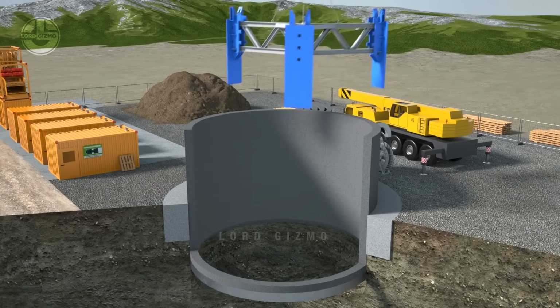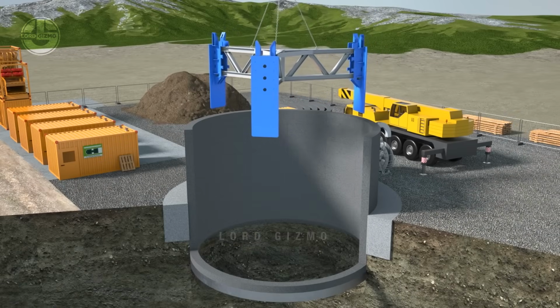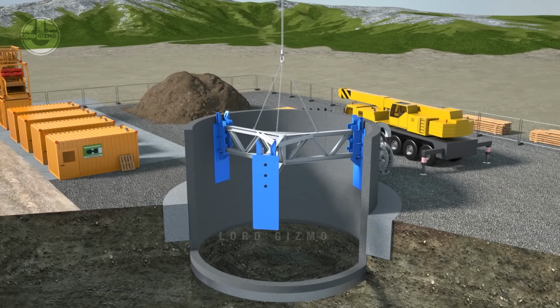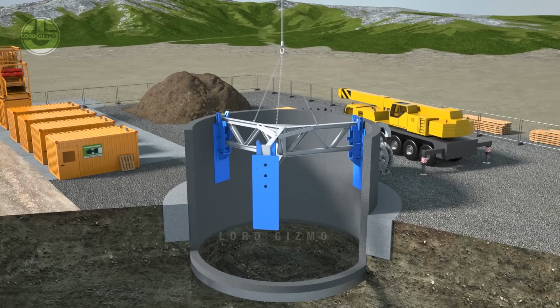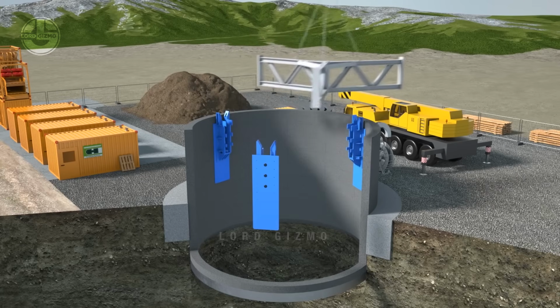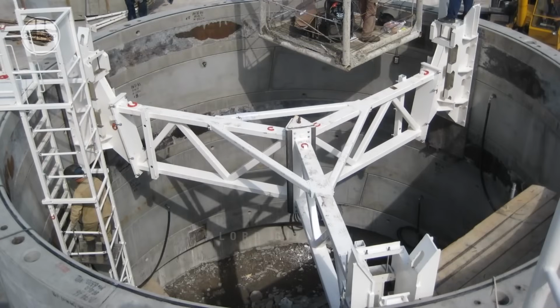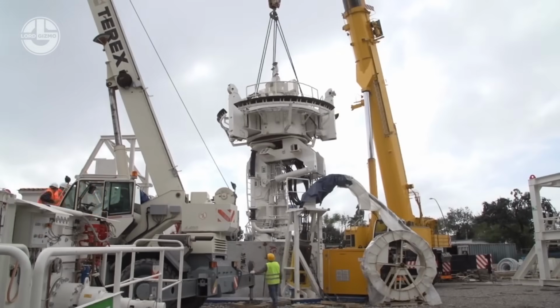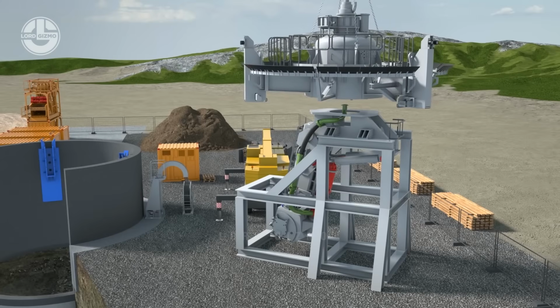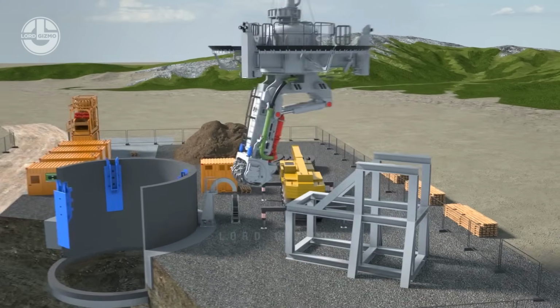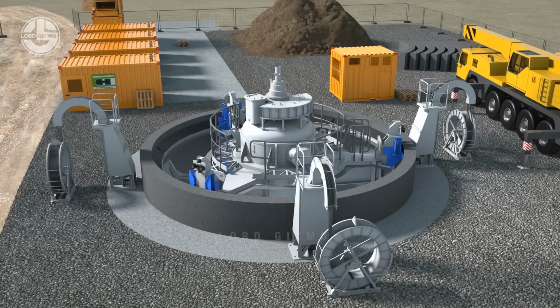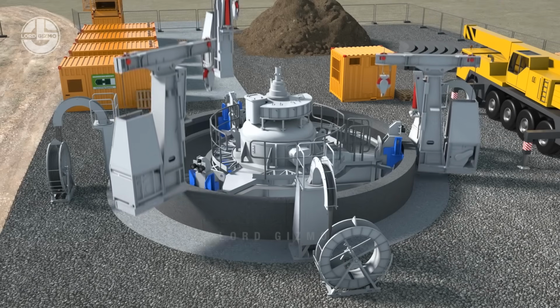Then, the machine installation starts with a dummy frame to position brackets for the machine arms. They will be welded into steel plates that are cast into concrete segments. Using a mobile crane, the VSM machine is built with the proper arm lengths and raised into the shaft. When the shaft is finished sinking, 3 winches are utilized to lift it out and perform routine maintenance.